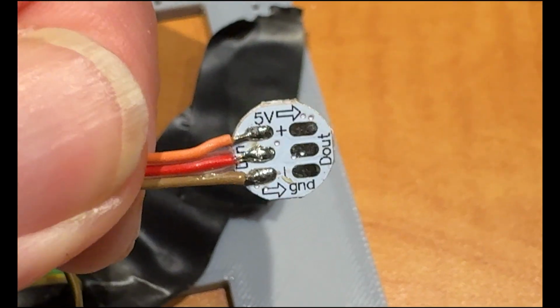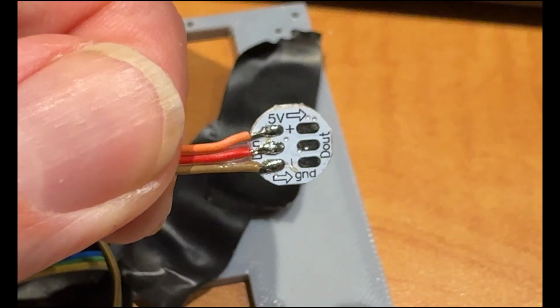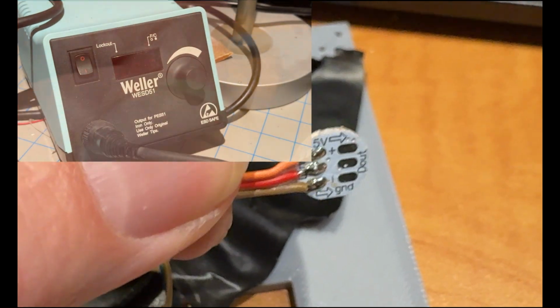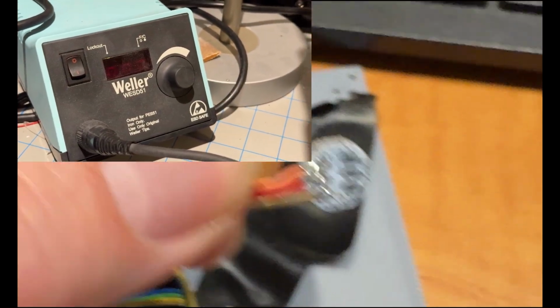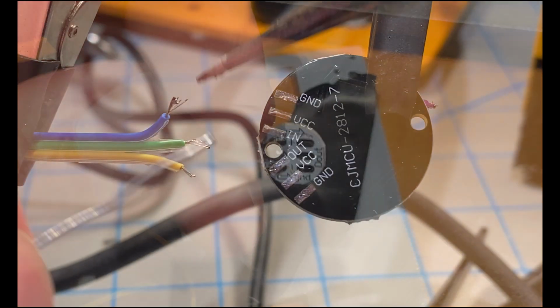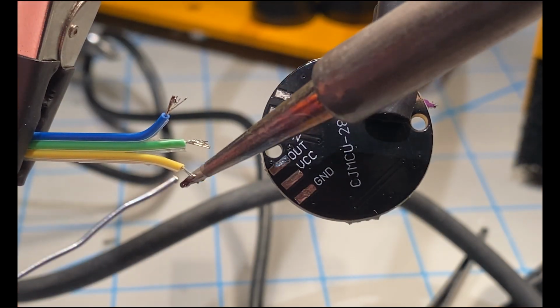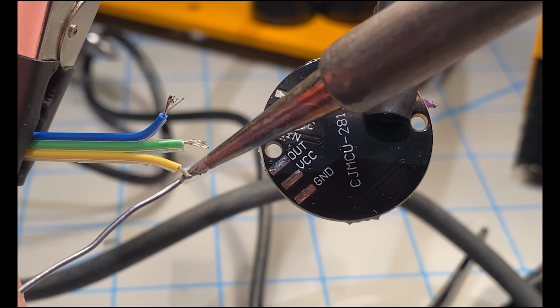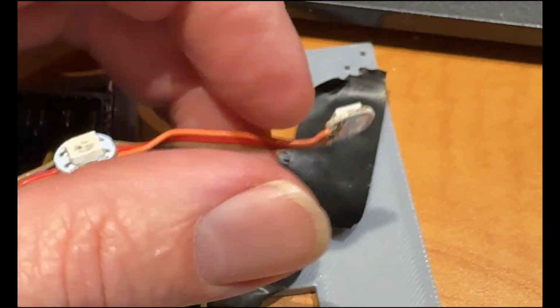So here's one of the single LEDs I was using. They are a pain to solder. I've got a Weller with a really small tip, which is nice for the WS2812B. I tip each one of them with solder, the wires that is, before I try to get them on there. So you have to do a lot of practice.